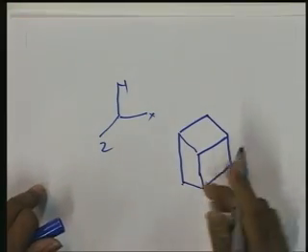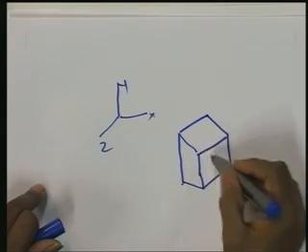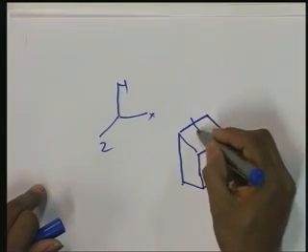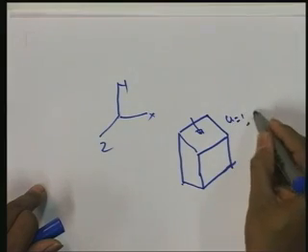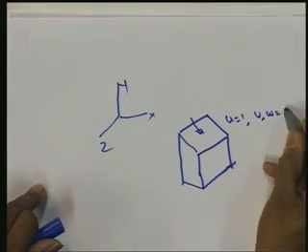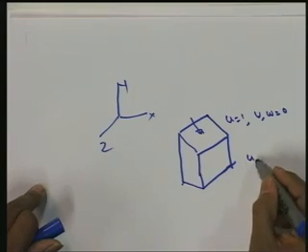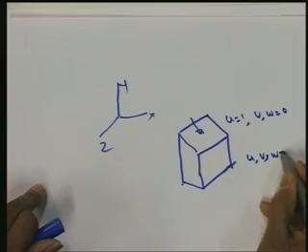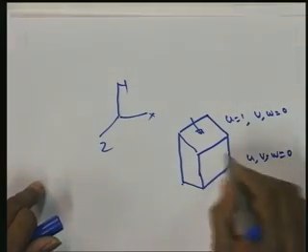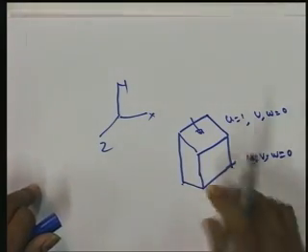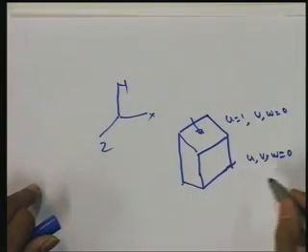For example, consider the incompressible viscous flow in this cavity, and let us assume that this lid is moving with a velocity u equal to 1, and v and w are 0. On all other sides also u, v, w are equal to 0. This can be a typical cubic cavity problem, which is generally used to develop computer codes using the Navier-Stokes equations and for verification purposes.